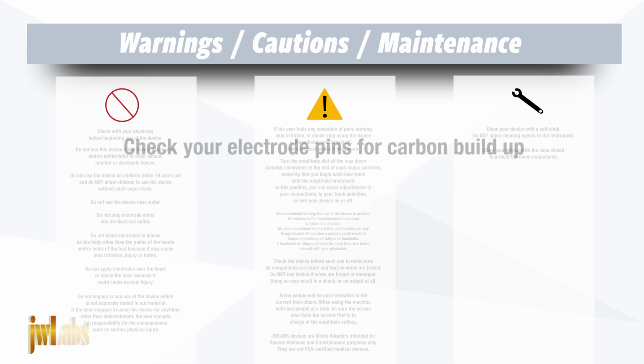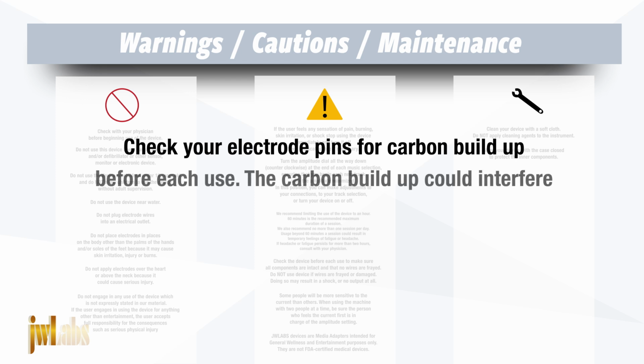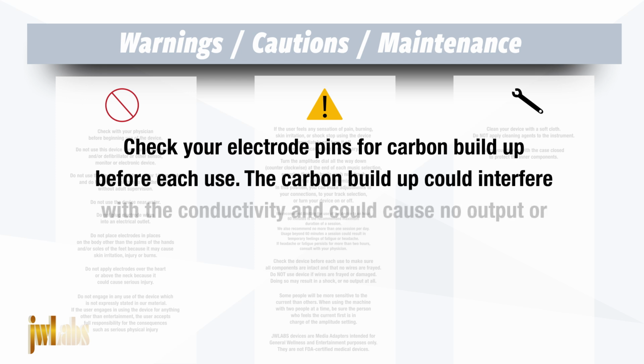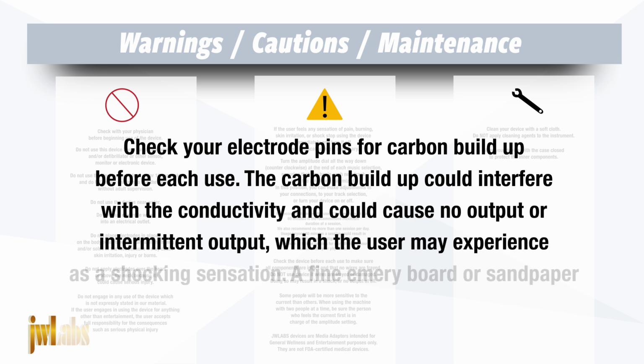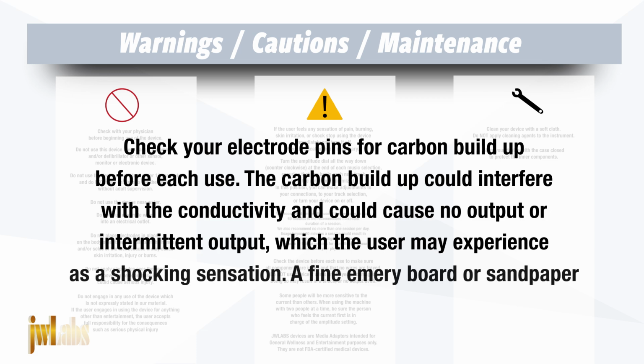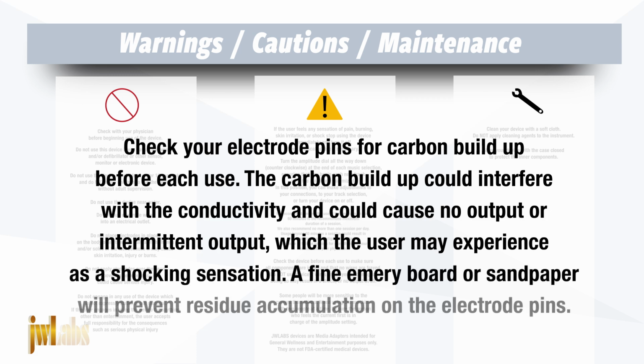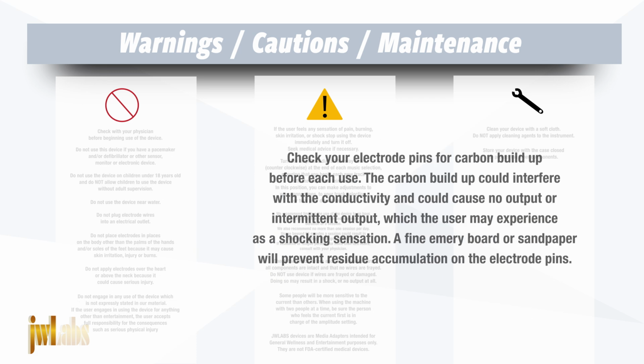Check your electrode pins for carbon buildup before each use. The carbon buildup could interfere with the conductivity and could cause no output or intermittent output, which the user may experience as a shocking sensation. A fine emery board or sandpaper will prevent residue accumulation on the electrode pins.